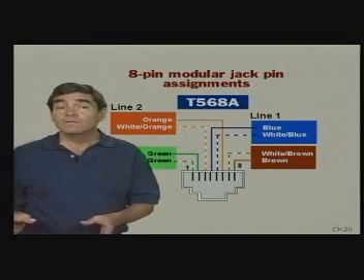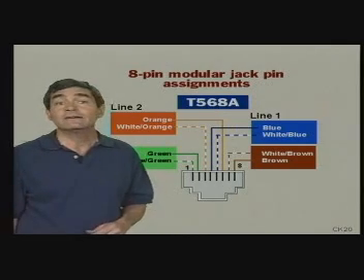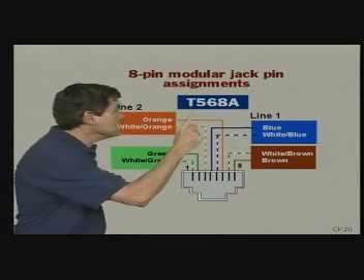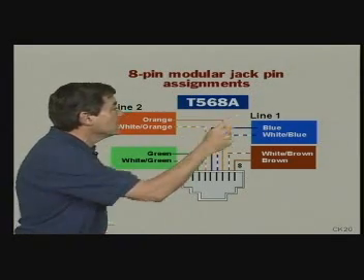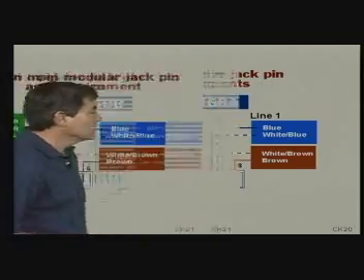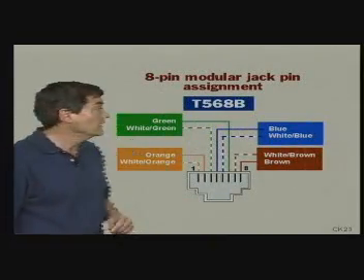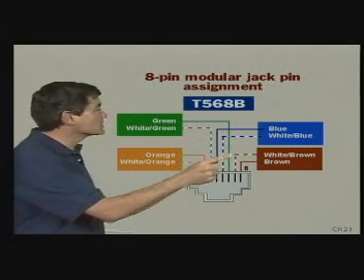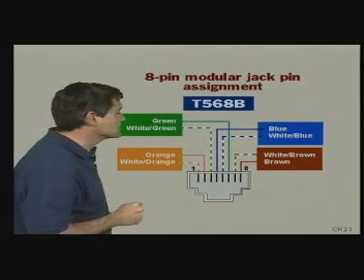Now, this wiring configuration is also standard for the commercial TIA 568 specification and is referred to as the T568A wiring configuration, or just the A configuration. Now, there's an alternative 8-pin wiring configuration called the T568B. Now, this configuration swaps the green and the orange pairs on 1 and 2 and 3 and 6.